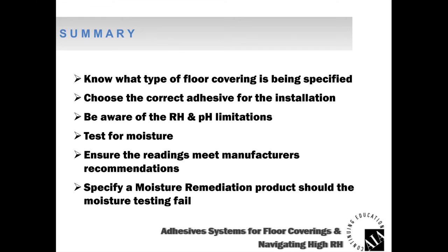Ask the questions. Test for moisture to know where you are. Ensure the readings meet all of the manufacturer's recommendations. And if necessary, utilize or specify a moisture remediation product, should moisture testing fail. Okay, pretty simple. It's basically just smart, good business practice. Keep those things in mind.